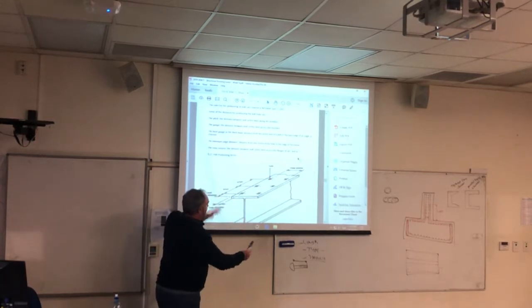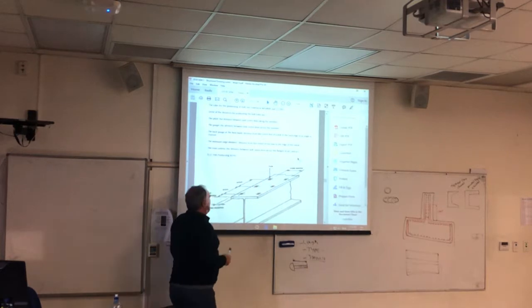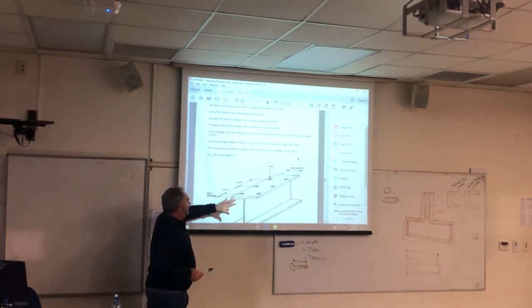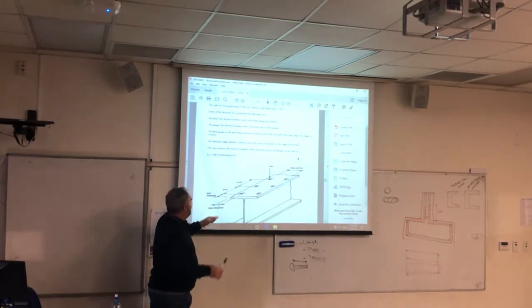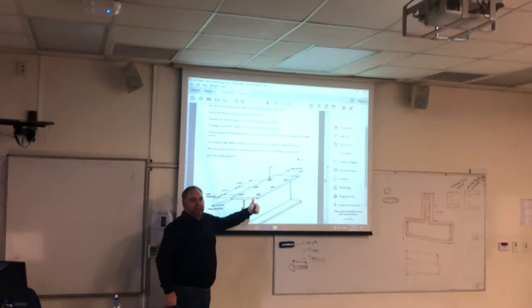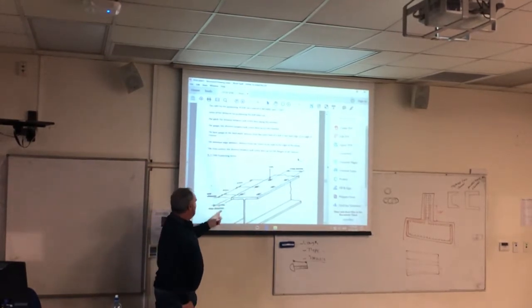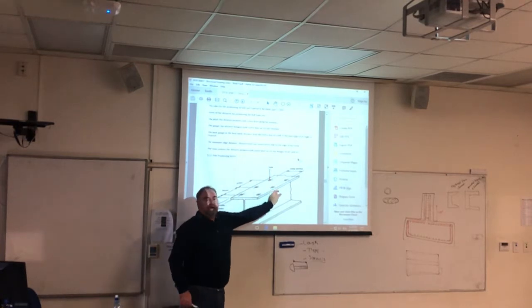Across, we call them the cross centres. At the end and the edge, the difference is that the edge is off to the side. The end is the very end of the steel member. You've got the end distance and the edge distance along the side. Okay?